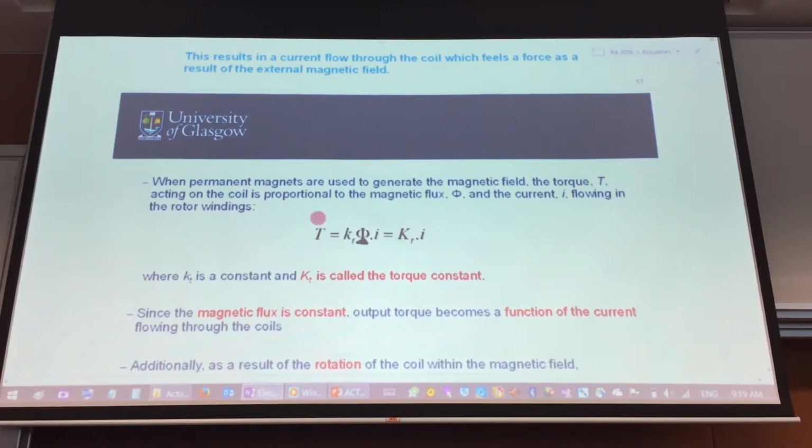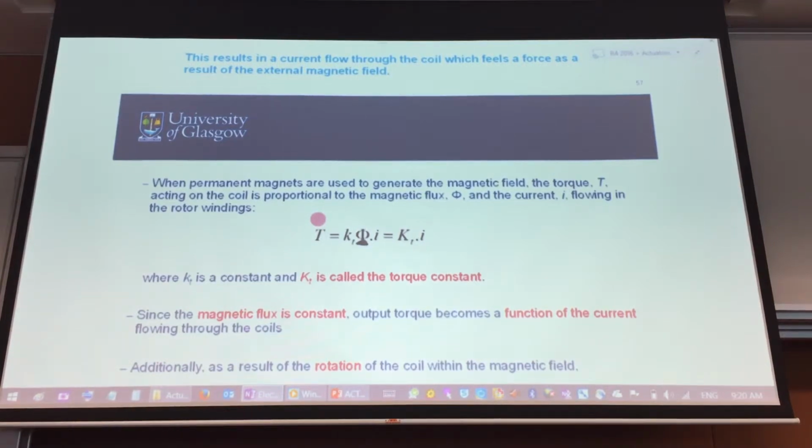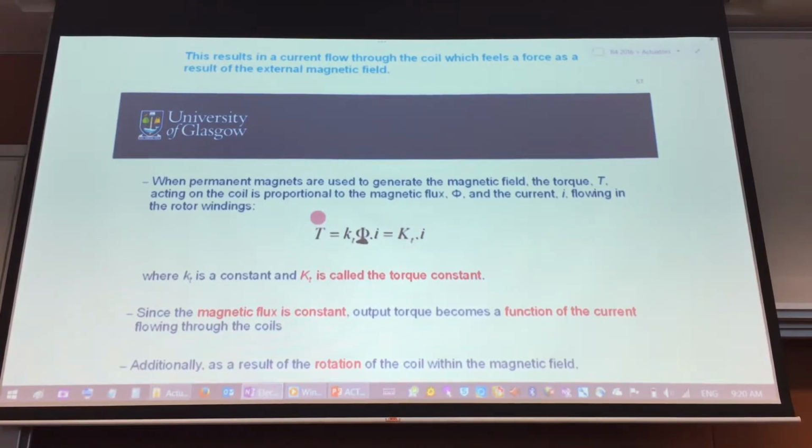But there's a limit to the amount of current that you can put through a motor. If you have heard before, oh, my motor burned up, the likely culprit is that there's too much current going inside the motor. How did that happen? Well, when you try to use your motor to drive something, you find that, wow, it actually couldn't move that thing. Let me give it more power. That more power gives it more current. And under a higher amount of current, if it's not within the design spec of that motor, it's going to melt down, it's going to burn your motor.